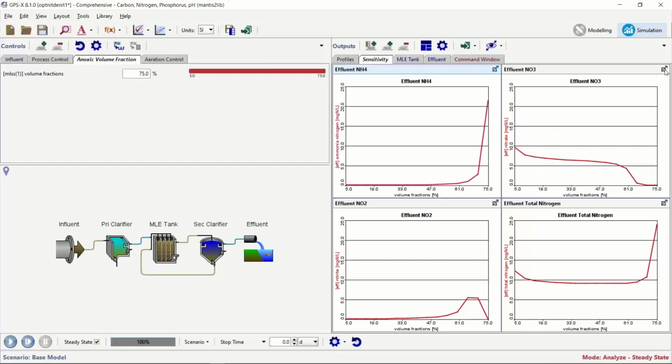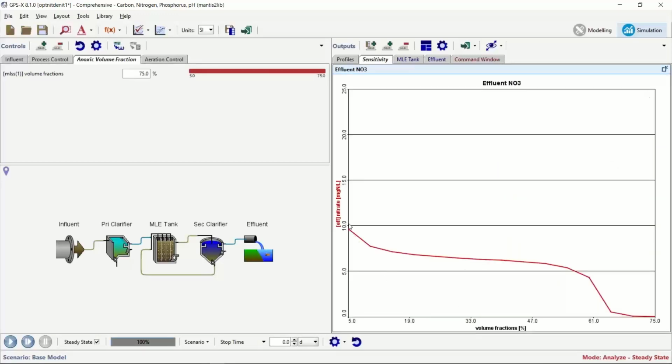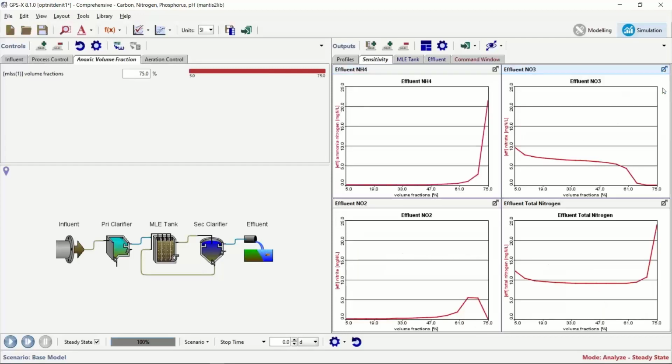It's interesting to see what nitrate is doing. Here, when it's got full nitrification but not very much anoxic zone, where we're not really doing any denitrification, then there's some sort of better spot in the middle here where we're doing both. And then once we lose nitrification, well, there is no effluent nitrate to accumulate, because we're not producing it in any way.